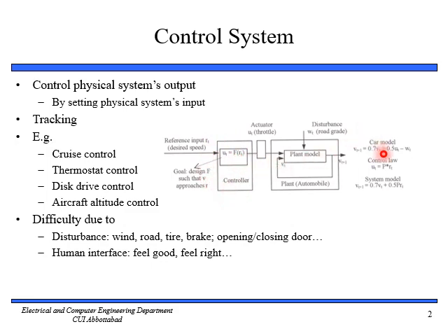Here's the control car model. V of t plus 1, that is the next state, next velocity or speed, is equal to 0.7 v t plus 0.5 u t minus w t. This w of t is the disturbance, this 0.5 into u of t is the input, where u of t is the throttle input, and there is 0.7 v t. So this whole thing makes up the car model, and this is the control law.